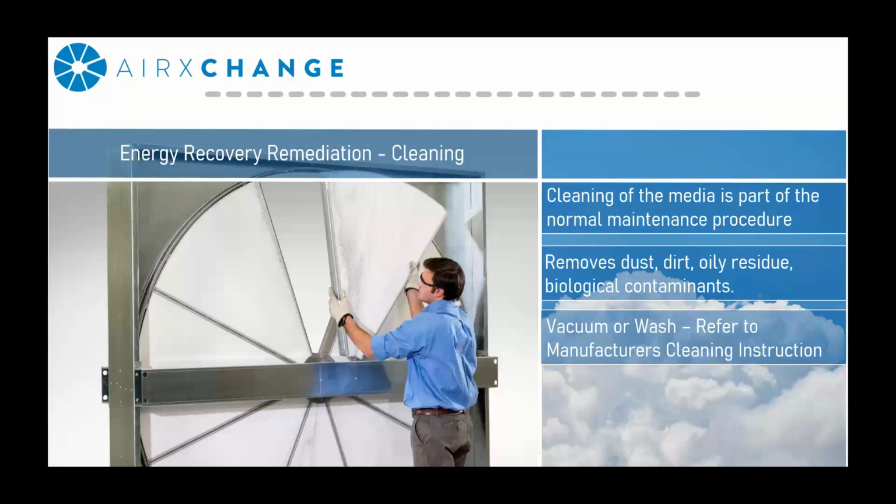Cleaning the media is going to remove dust, dirt, or any type of residue and biological contaminants from the surface area. The most common methods for performing this task are either vacuuming or washing the media, depending upon the manufacturer's approach. For air exchange energy recovery wheels, if they look like the one in that left-hand picture, we recommend that you wash the heat exchanger media, as we find that gives you the best result. The media itself is segmented in design, so you can remove the transfer segments from the wheel frame and wash them in a soapy solution.